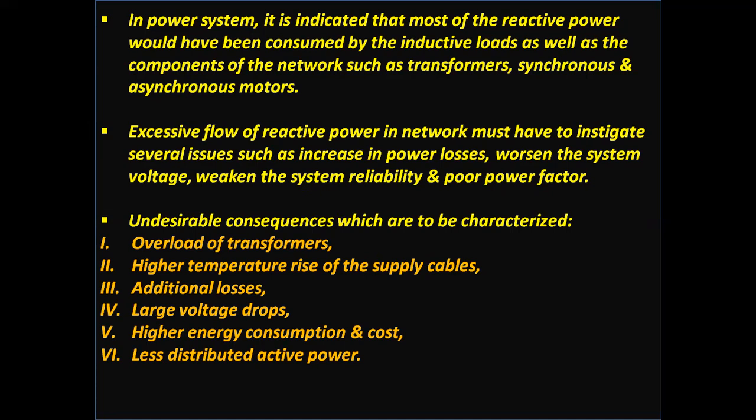Undesirable consequences are characterized as follows. One, overload of transformers, higher temperature rise of the supply cables, additional losses, large voltage drops, higher energy consumption and cost, less distributed active power.